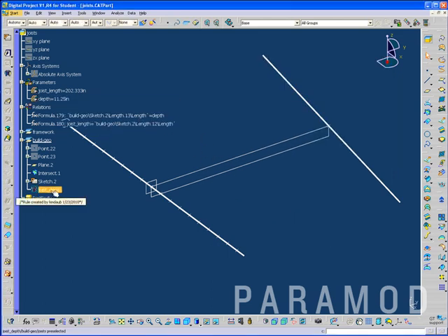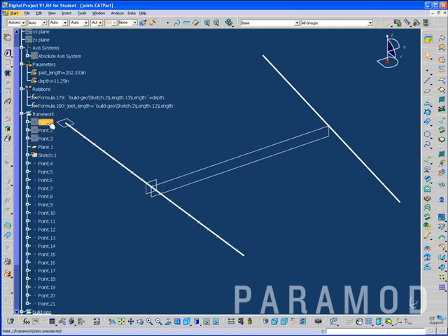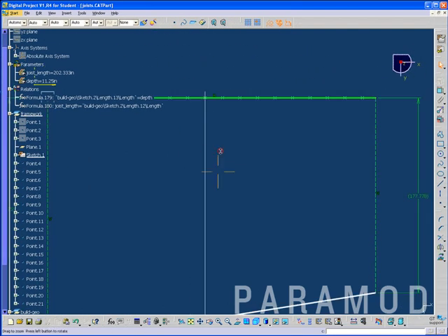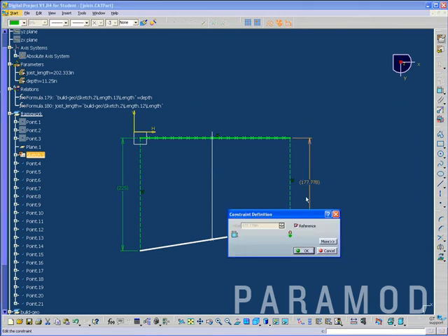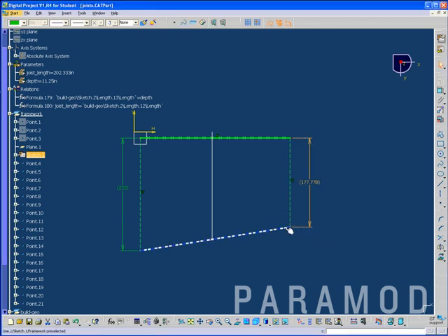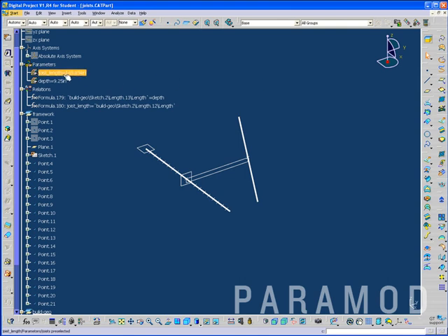And so what we might want to do is just test this. Currently, that's 11.25, that's a 2x12. So if we go back to our first sketch in the framework and reduce these numbers down, we don't need to change that number. I can reduce this down. And now we see that the joist length is 149, and it's now a 2x10. And so we know that the rule is working.